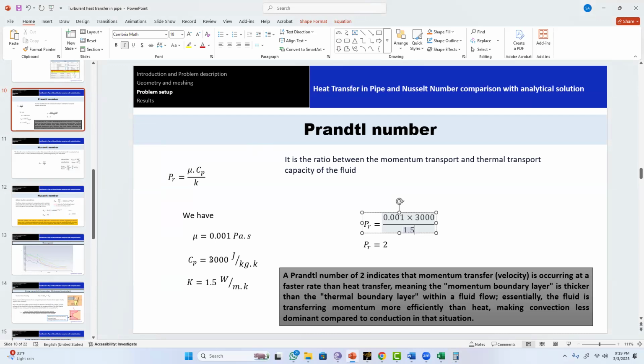So it will not store the energy inside the water, but rather transfer the energy from the wall to the fluid. If the Cp is higher, you will see the temperature rising in the fluid. If the Cp is lower, you will see the temperature rising on the wall. So if you increase Cp, you will see more temperature gain in the fluid, but if Cp is lower, you will see a high temperature change on the wall surface. That's why I wanted to see some change on the wall surface. Otherwise, it was showing very small values, so I made this trick here.